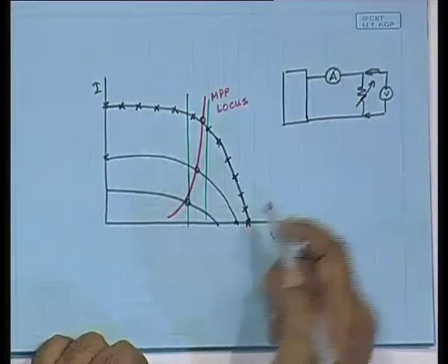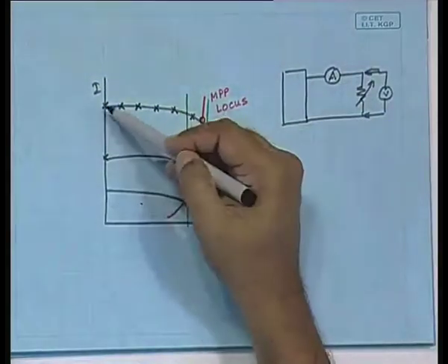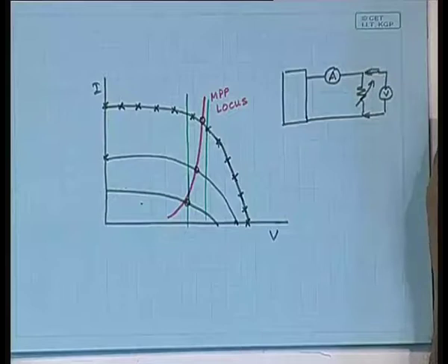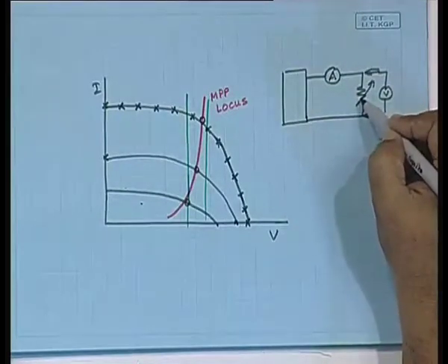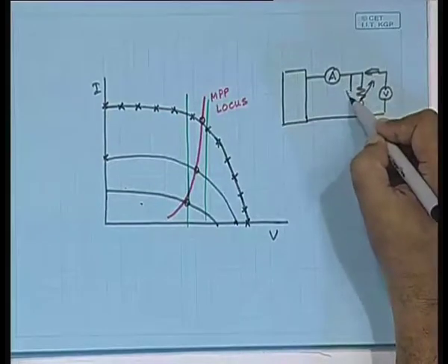So, while you do the experiment, the energy students will have to do the experiments sometime later when you come to that particular course, the laboratory course. There actually you will have to plot it while taking each reading. So, each reading is taken, take the value of the voltage and current, there is no point writing it down, just plot. Thereby you see whether I am getting equally spaced points or not, whether I am getting the proper curve or not, and then simply open this, you get this point, simply short circuit this with a switch, you get this point. Clear? It is not simply making these resistances 0, because some lead resistances remain, simply connect it with a switch, this has to be there